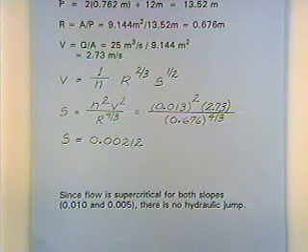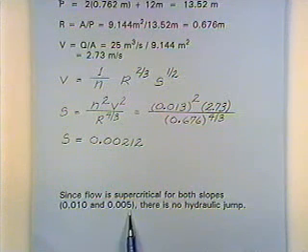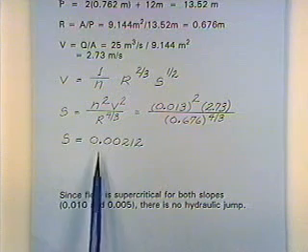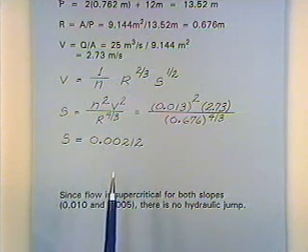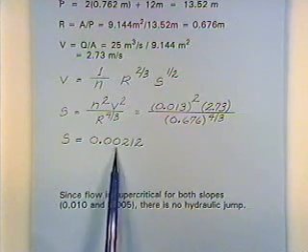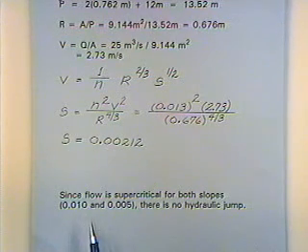And so then I've got to think, what is it I actually have? My real actual slopes are 0.01 upstream, 0.005 downstream. And so I need to have supercritical flow upstream, subcritical flow downstream in order for the hydraulic jump to occur. And so to have supercritical flow, the slope has to be steeper than 0.00212, and 0.01 is steeper, so I do have supercritical flow upstream.